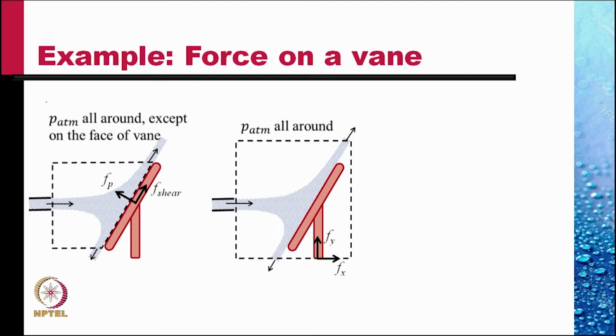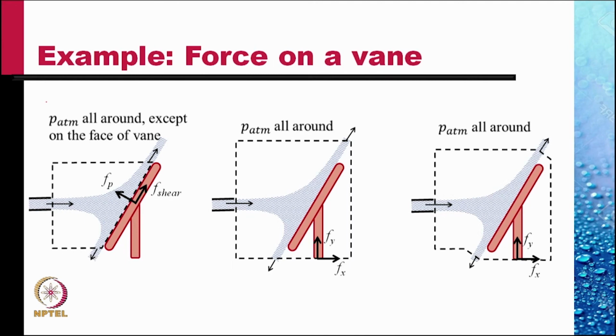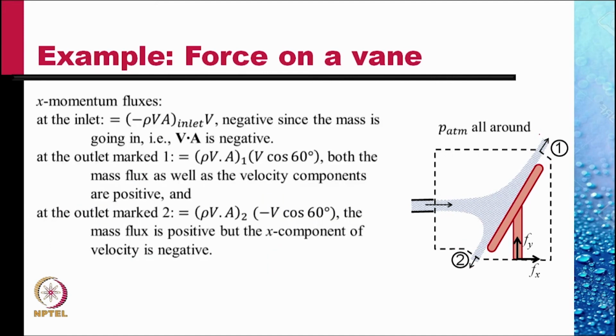but we can improve upon this a little bit by considering the area of this control volume as normal to places where there is water influx and water efflux. So just minor changes here and here to make the control surface normal to the velocity at this end. So we'll work with this control volume. We'll first work with the x momentum.